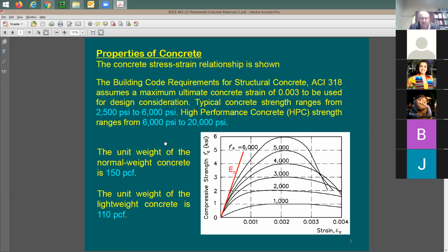This can be like if you're buying a vault, you guys know the electric vault, or let's say a catch basin. You guys know what I'm talking about, right? Certain precast elements and members that you can just buy and use are going to be maybe 3,000 psi at least. No one is going to be using 2,500 psi in the precaster because you'd like to gain lots of strength in a short time, so they're able to use the form again. So it could be maybe 3,000, 4,000 psi at least.